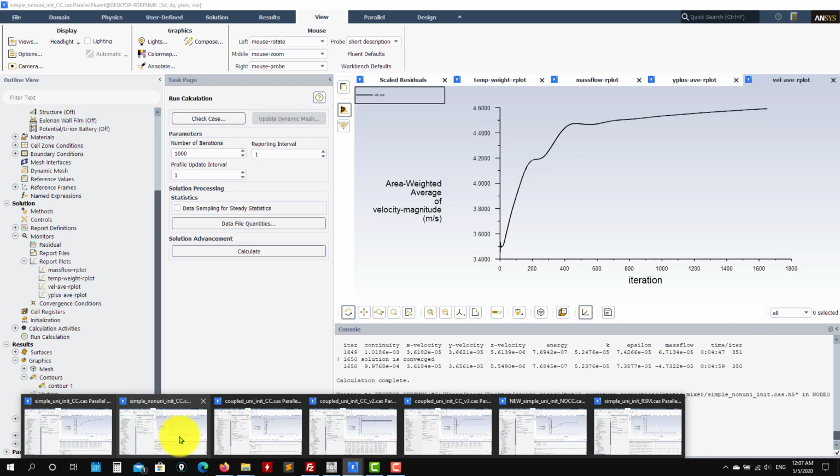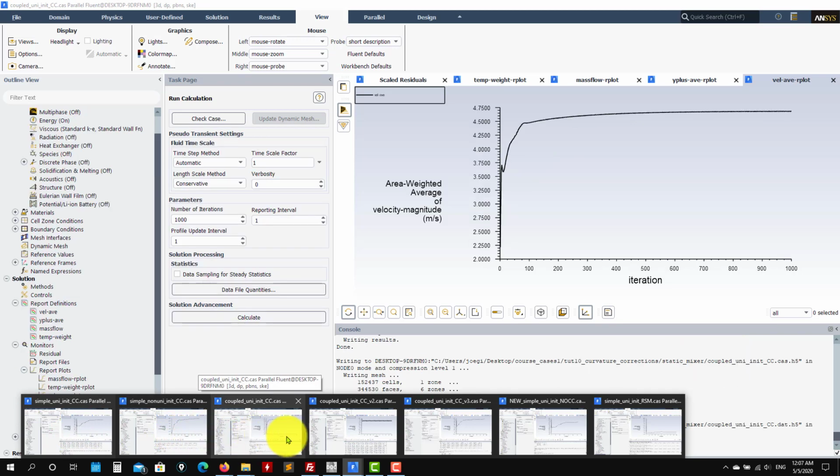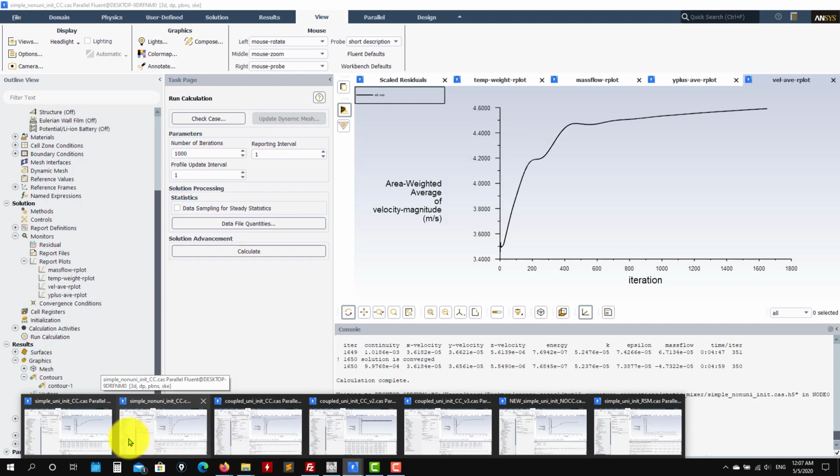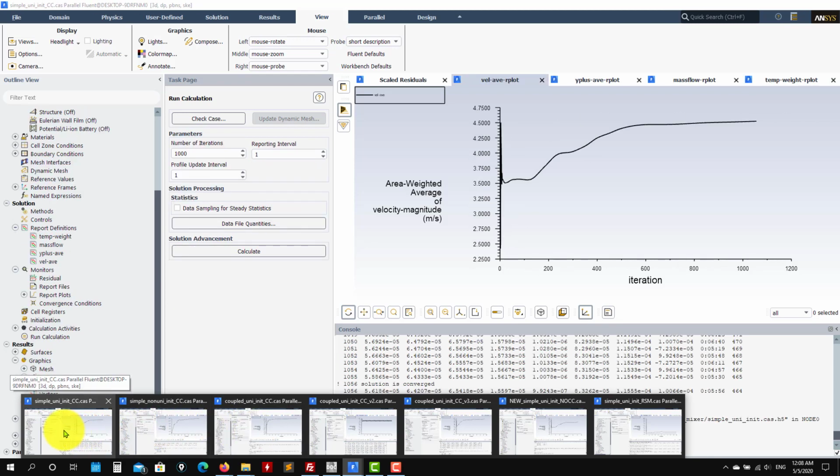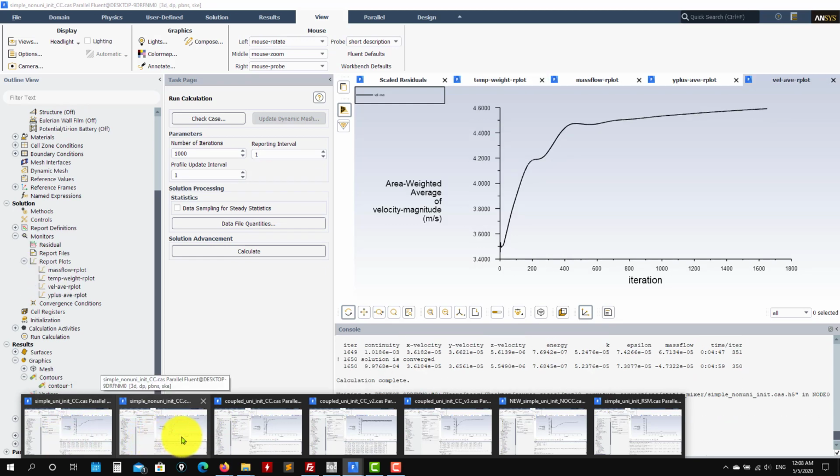See that different solvers will give you different behavior. So probably this is the ideal one, that at about 500 or 600 iterations it is already flat. Okay, this is what we want. Instead, in these cases you need to iterate a little bit more, or much more here, to get it flat. And in this case it's probably also flat. See that they're all flattening at about the same value.